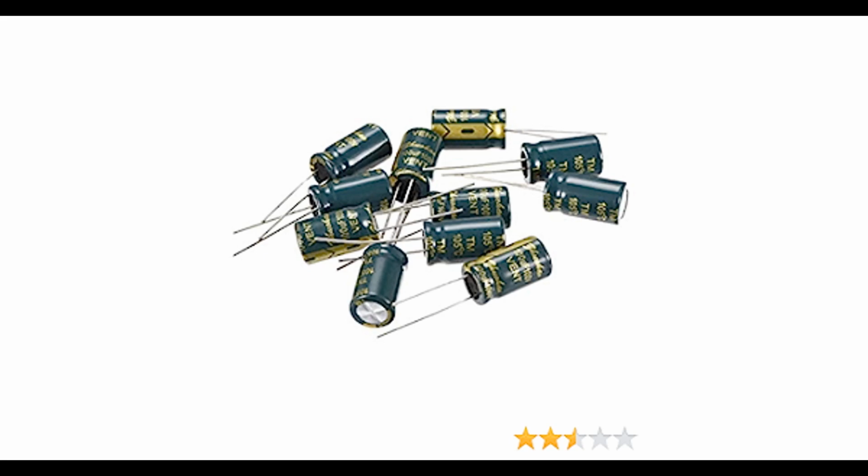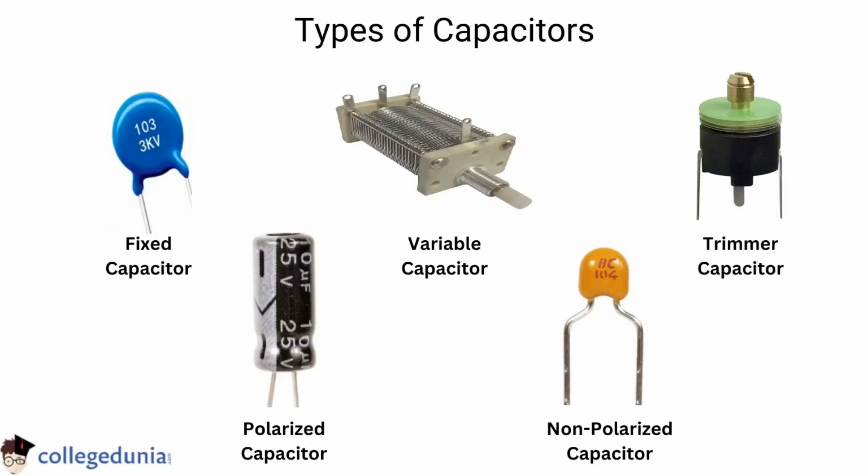They are suitable for circuits that require smaller capacitance values and lower voltage ratings. Tantalum capacitors are also known for their low leakage current and stability, making them suitable for precision and low-power applications. It's important to select the appropriate type of electrolytic capacitor based on the specific requirements of the application, including voltage rating, capacitance, size constraints, and temperature stability.